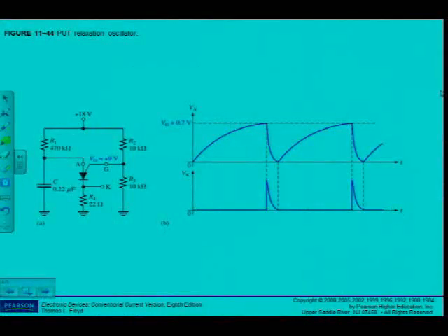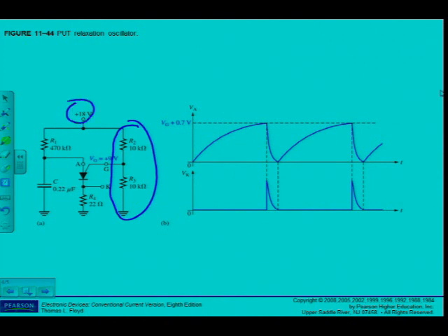As I can see here, the voltage divider that we've discussed earlier, R2 and R3, has a supply voltage of 18 volts. But with my voltage divider here, I can see that the two resistors are of the same value, so it will halve the voltage, so that I have a VG of 9 volts.